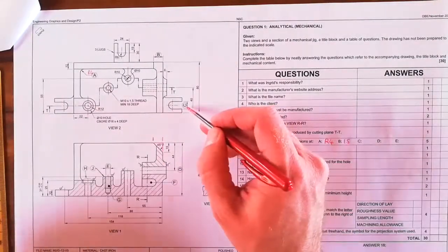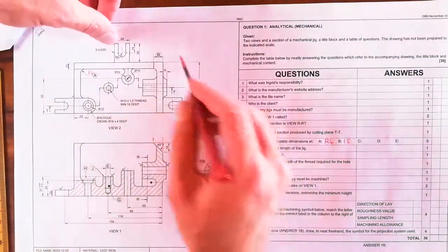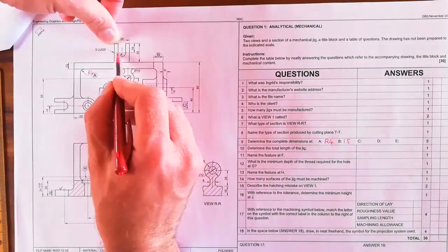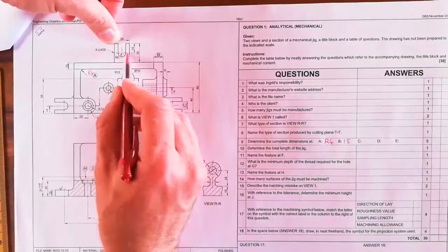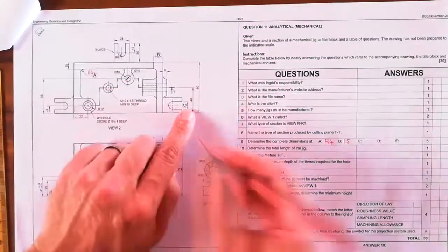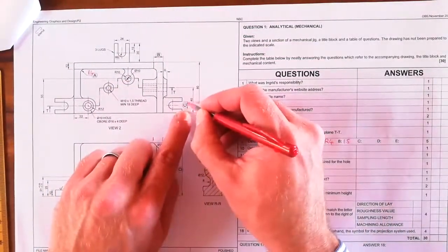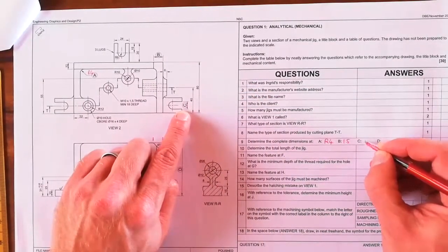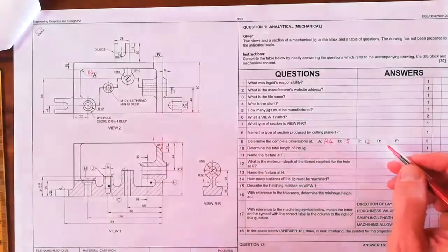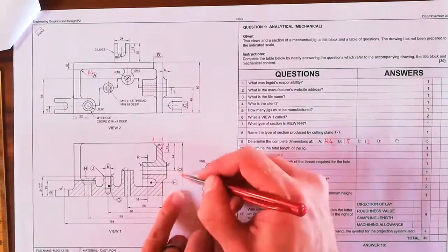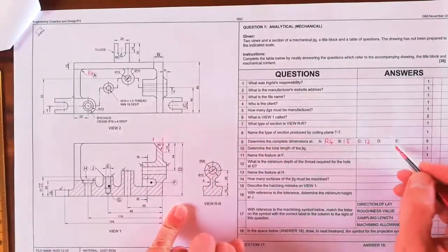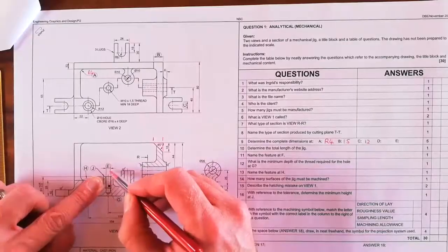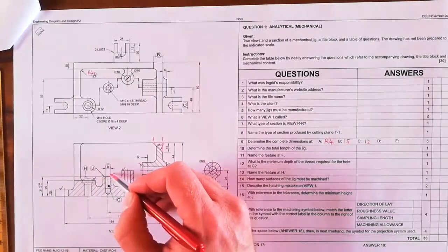C, how do we get C? If you look here on top, they actually tell you radius 6. It's for this arc here. Now, if I have 6 and 6, it gives me 12. Now, this measurement, it's a measurement symbol here. It's not the radii or diameter, so make sure you can just write 12 there. And then D, that one you can calculate. That's easier to do. And E is the other one that I wanted to show you. That is your internal screw thread here, and that's going to be diameter 7.